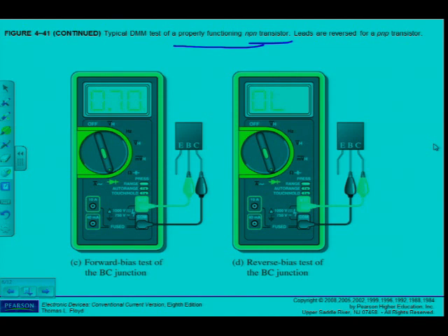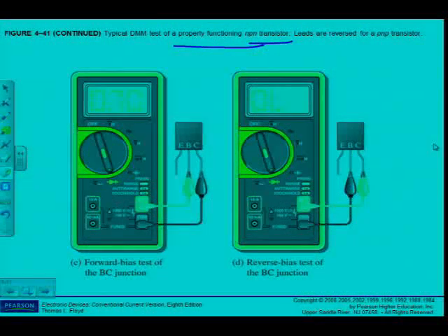What faults may occur with a transistor? Same as we had with the PN junction, the other device that we've discussed, the diode. The diode could either be open or shorted. Normally the most common fault is being open. Because I'm testing one PN junction at a time for a transistor, if the junction is open, then if I forward bias and reverse bias that junction, I would get the same value, which would be open line, or the value of the internal battery of my multimeter.